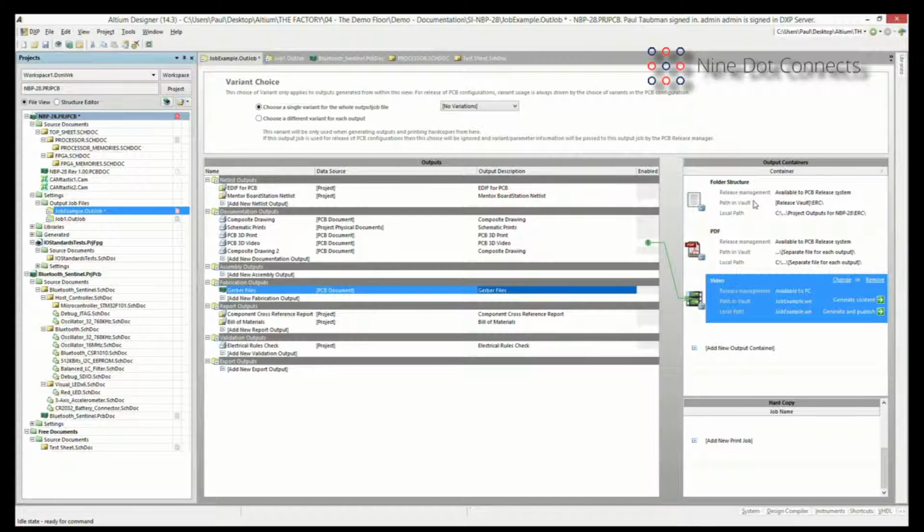It's taking information from Altium and putting it in the right format to get it into your file structure. So if I was to rename this, I wouldn't call it a container, I'd call it a distiller, okay? Now, there are 3 different types of containers in Altium Designer, and let me go through each one of these very briefly. The first one is the PDF.